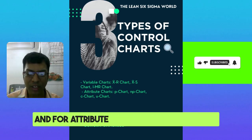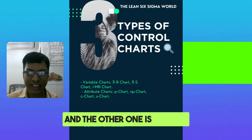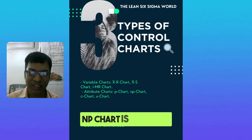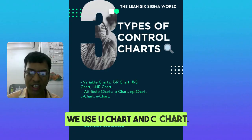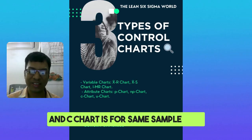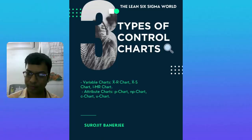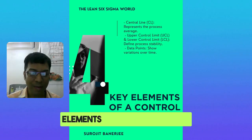And for attribute data or discrete data, there are two things: defective components and defects. Now for defectives, we use P chart and NP chart. P chart is for different sample size, NP chart is for same sample size. And for defects, we use U chart and C chart. U chart is for different sample size and C chart is for same sample size. So these are all the different types of control charts that are widely used in any Lean Six Sigma projects.